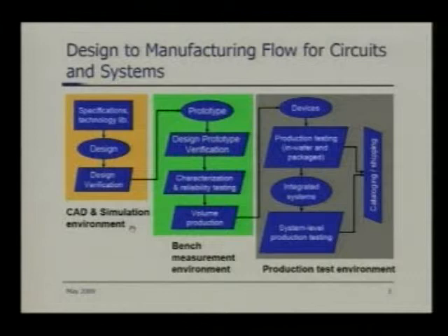Another ingredient that you will be using in the CAD and simulation environment is a technology library. For example, say you are designing a circuit and using National Semiconductor's fabrication facility to realize your amplifier design. In that case, you need the technology library which corresponds to the process that National Semiconductor uses for that particular technology node, meaning the VCC it uses, the channel length it uses, and so on.